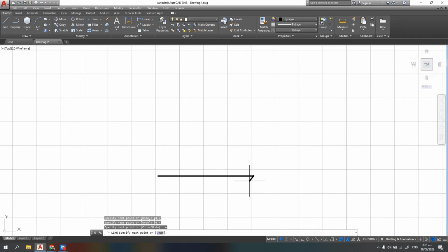With relative point of entry, that means every time you type coordinates, your origin moves. Okay, remember that. This is the difference from absolute. In your absolute coordinate entry, the place, the coordinate, since that is absolute as the word says, will not move.